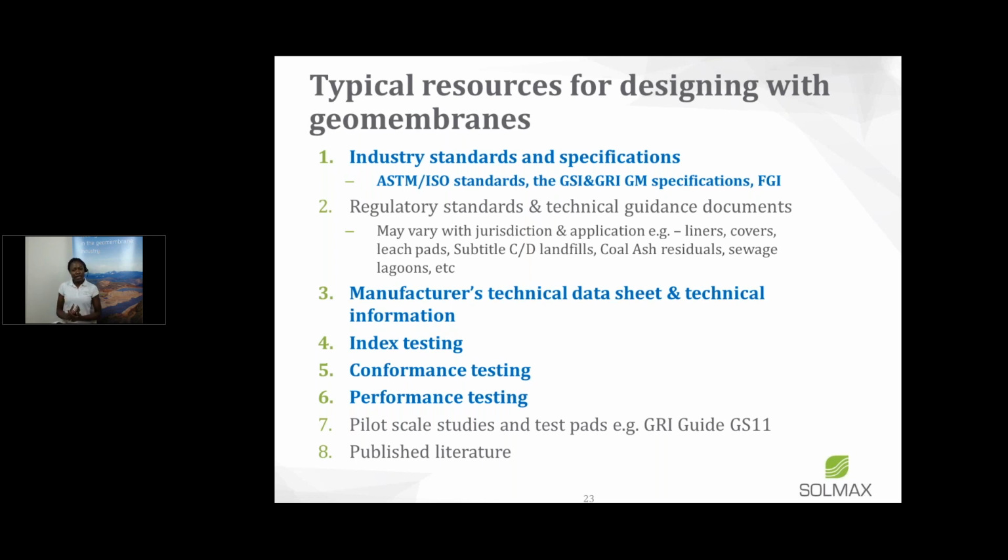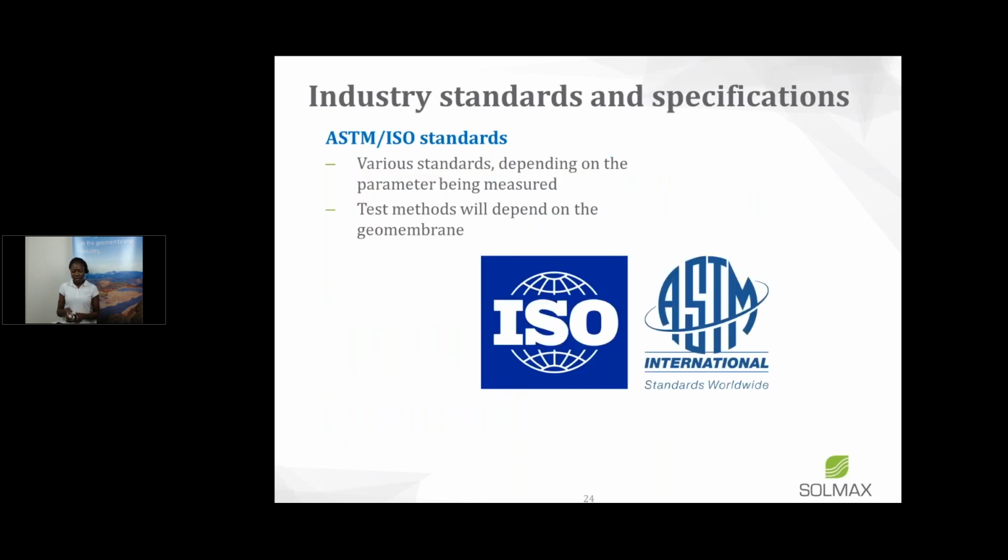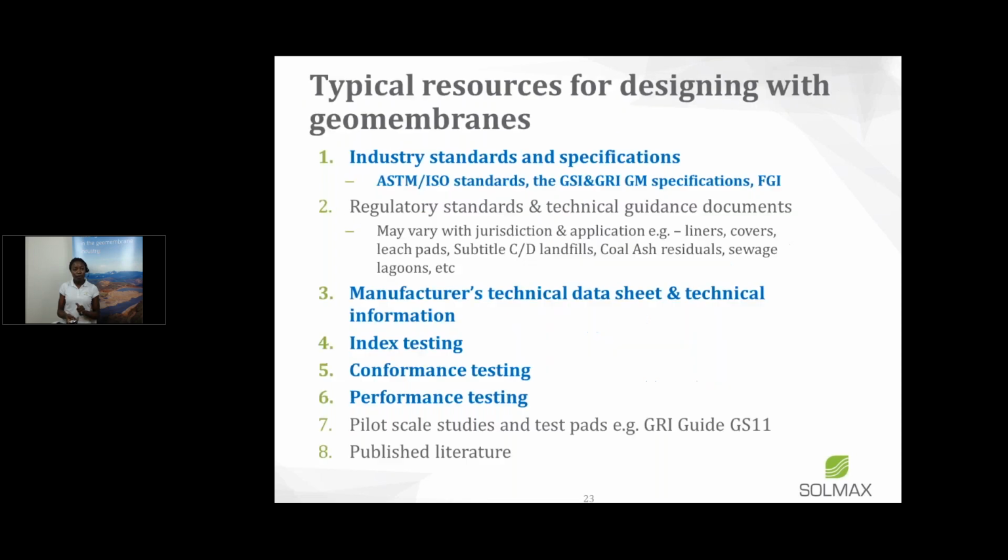And also there is performance testing. The performance testing is a little bit different from the index testing. The performance testing simulates the site conditions that you're going to have. So the material isn't tested as an individual component. It's tested as part of a system or under some specific conditions that are similar to what you're going to have on your site. And there are pilot scale studies and test pads.